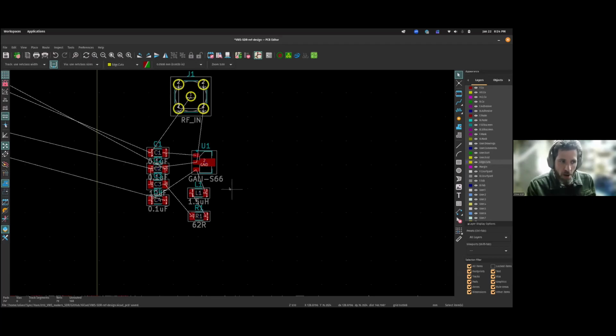Only once you have placement complete, start drawing the traces to connect everything together. Because inevitably you'll decide, oh, I actually want to move this capacitor slightly this way or that way, and if you then have to redraw the physical copper traces for that component, you'll redo a lot of work. So first step is do placement on the entire board.